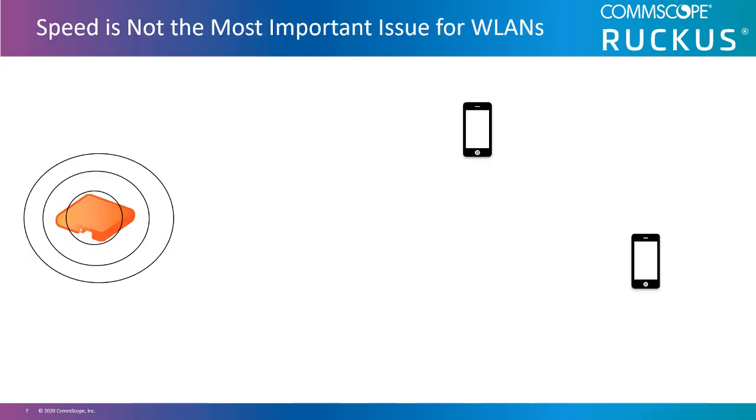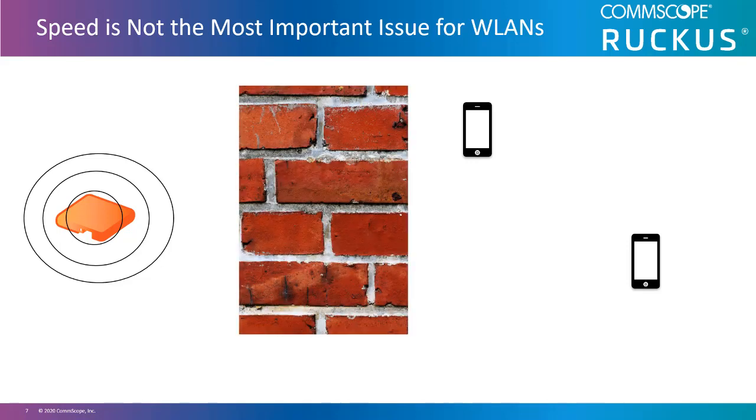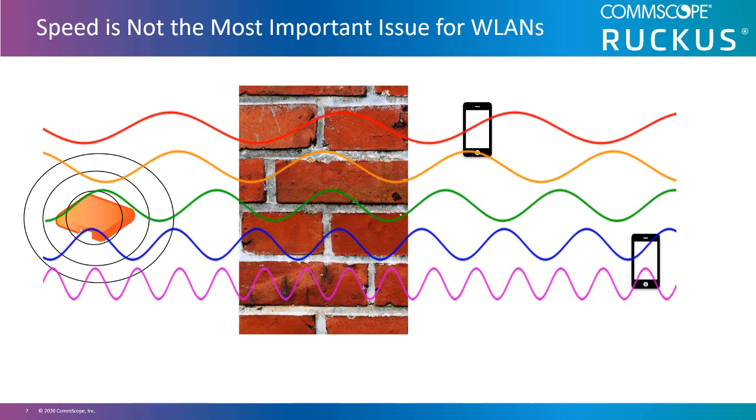Performance can vary widely based on range, obstacles, other signals in the air, multipath reflections, and the quality of your access point and your client device. To address these issues, 802.11ax aims to improve efficiency in a number of ways to give you consistently higher real-world speeds than what you get with the 11ac standard.